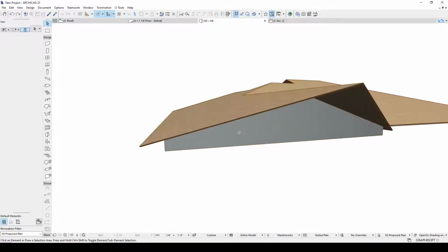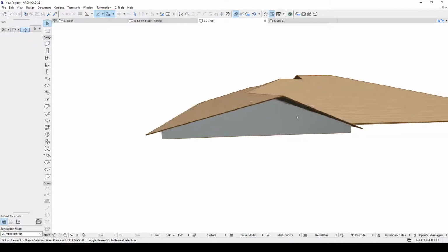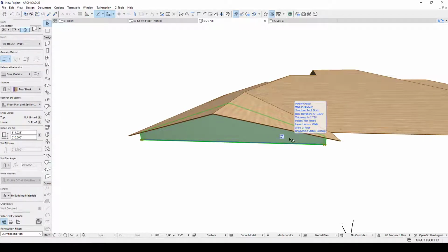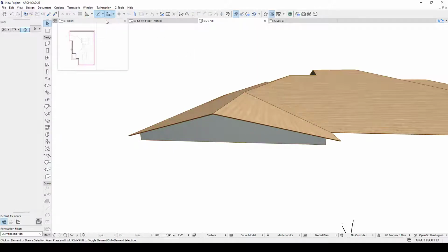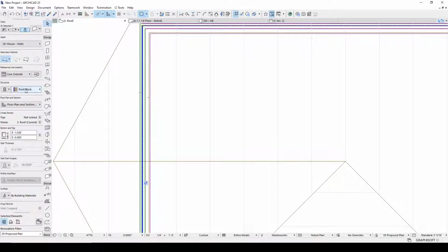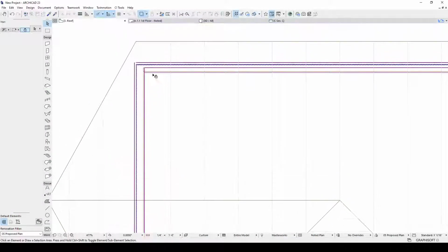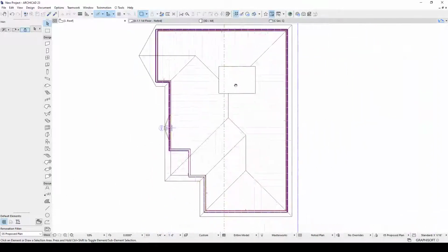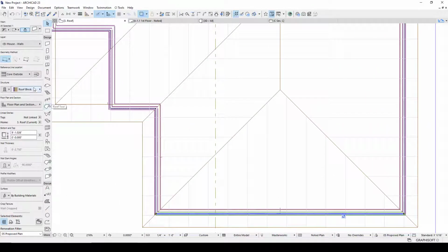trimming these walls. So here I have a gable, now I have a gable end. That's why I like doing this little wall fill. Now you might want to say, okay, well, this wall is now a gable end and it shouldn't be the little block anymore. So you could change that wall type to be the wall below. Let's look at that. And so now maybe this should be an exterior stucco plywood 4x. And that'll give you a true gable end just by changing the composite.